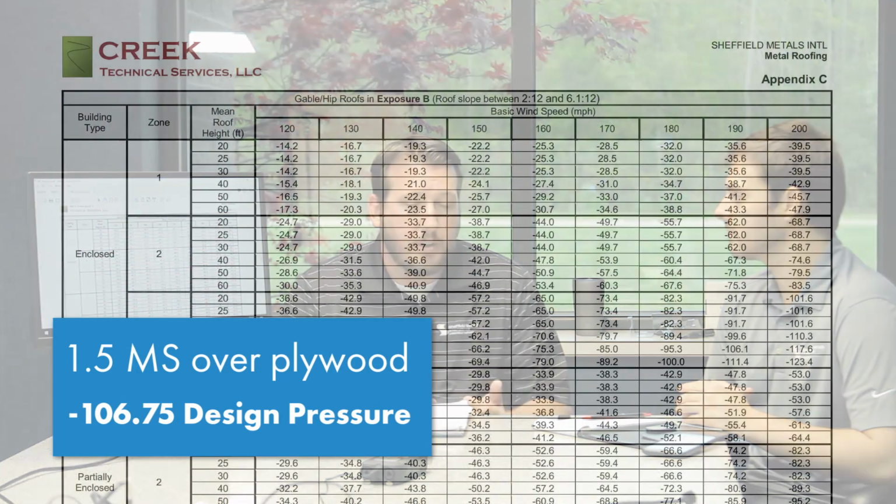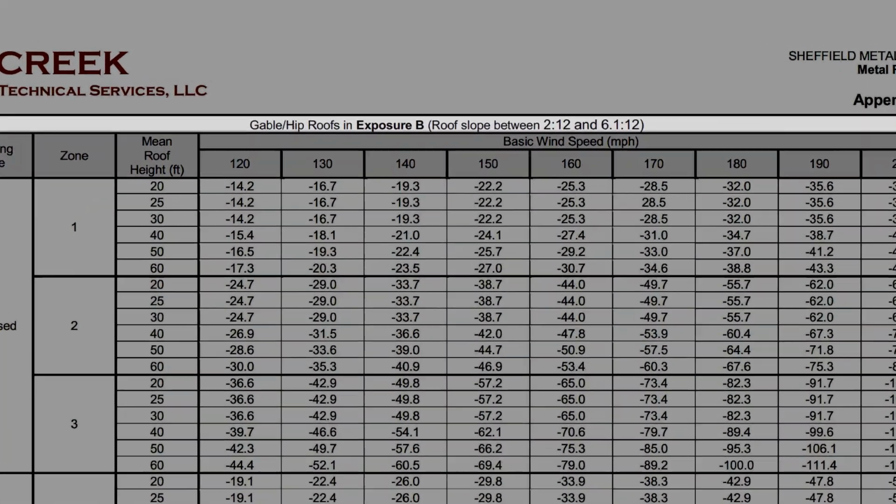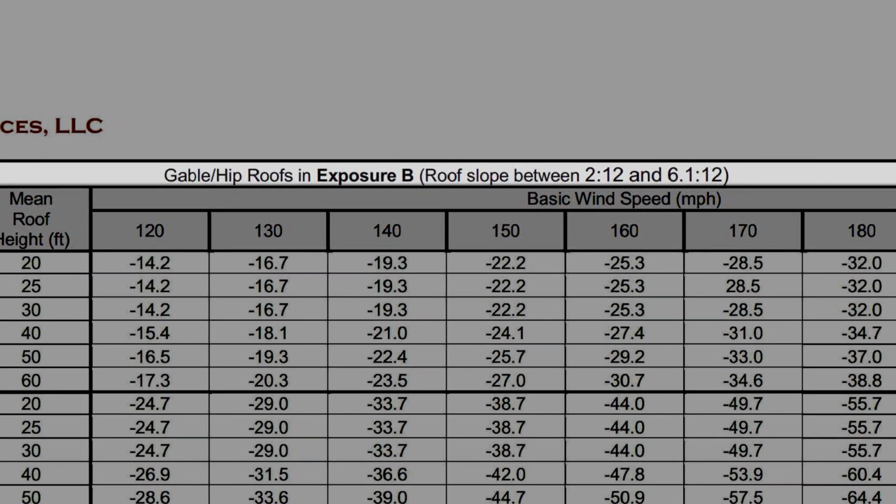So, like we talked about before, the design pressure that we used in an example was a 106.75 for the 1.5-inch mechanical over plywood. This chart, as it says right on it, is good for gable and hip roofs in exposure B for roof slopes between 2:12 and 6:12.